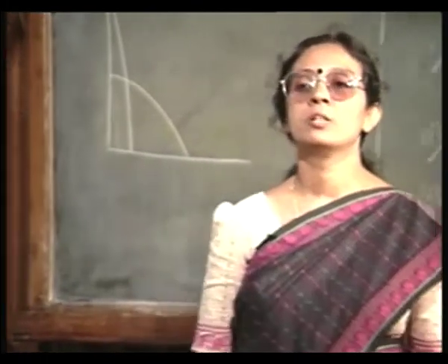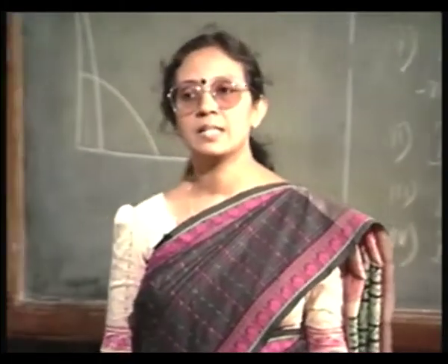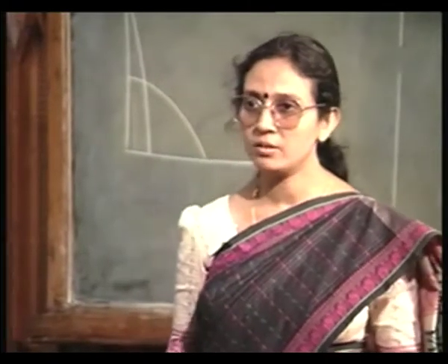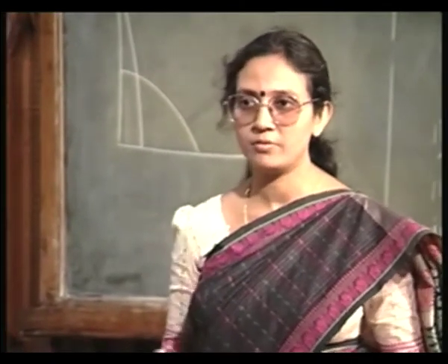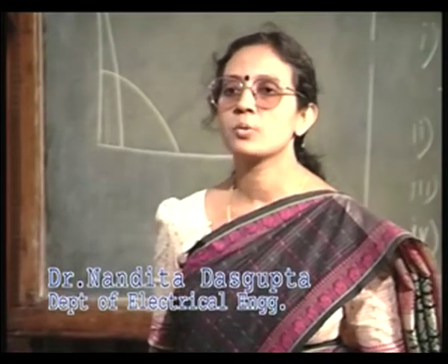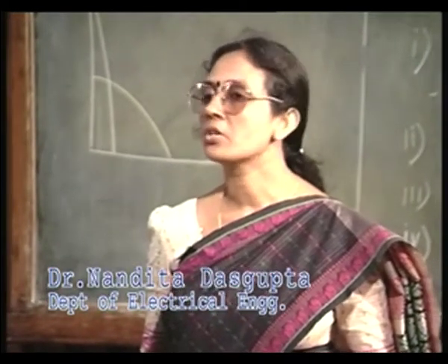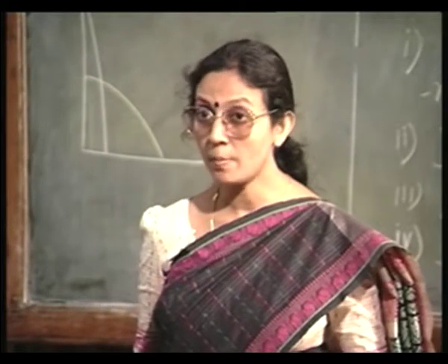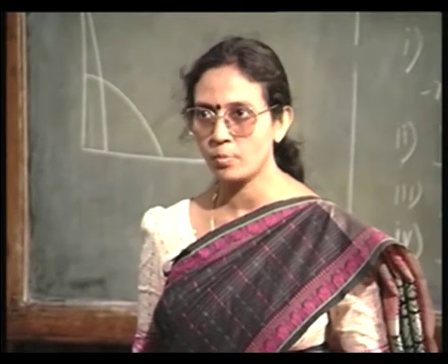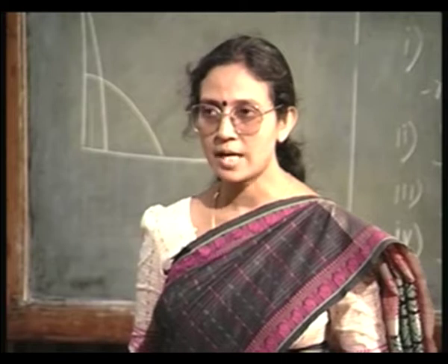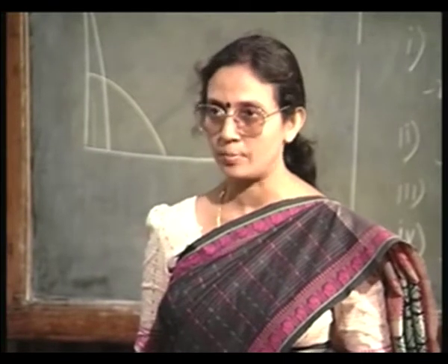Fortunately, for silicon, these annealings are done at comparatively lower temperature, by 950 degrees centigrade, as I said. At that temperature, the square root of Dt is not very high, it is quite small. Remember, the square root of Dt is a very important parameter. This actually determines the diffusion depth.